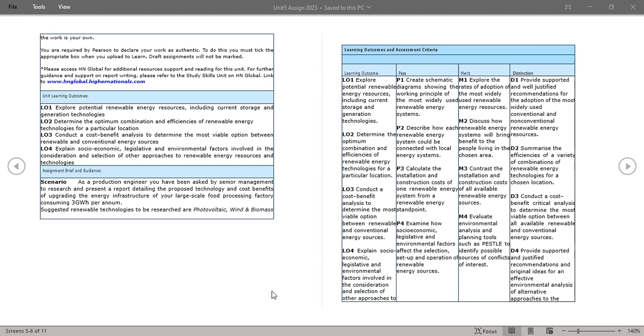Again, if you look at PV efficiency, if all other variables remain constant, looking at load factor, if the efficiency goes down, then the power output goes down, then the energy over a specified time period must go down, then that will affect the levelized cost of energy. It will affect your cost benefit analysis.